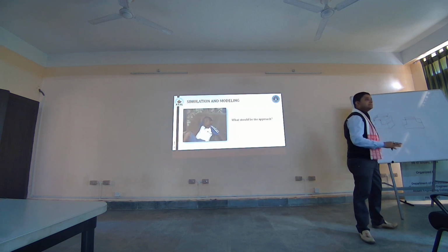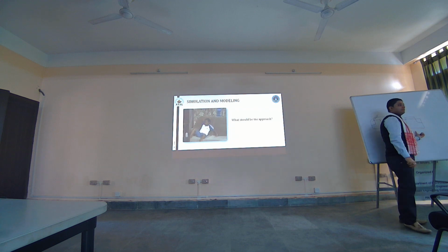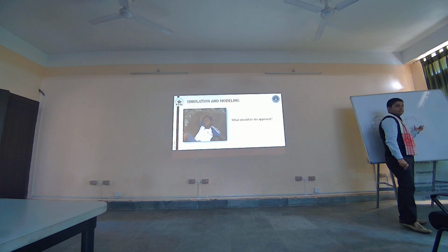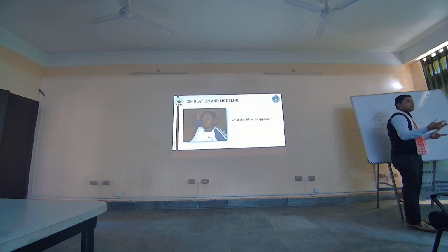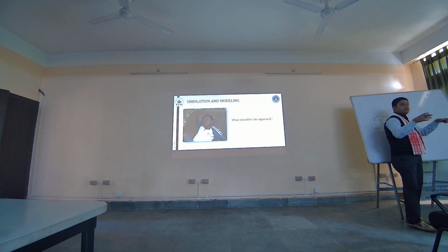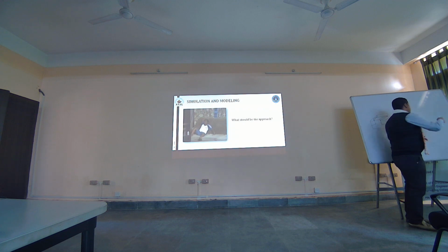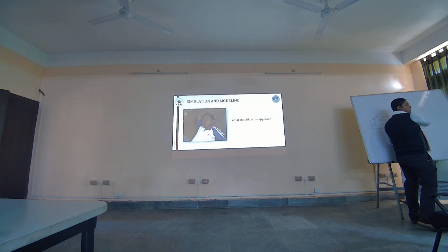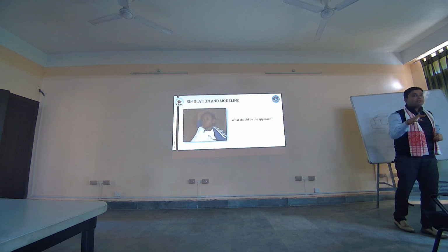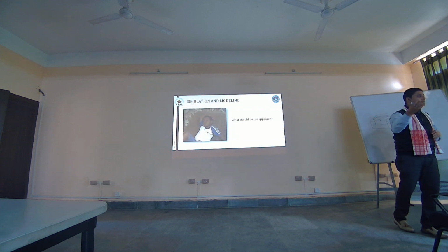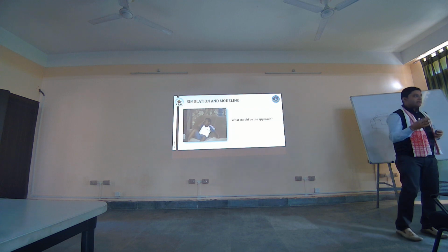Now, the problem with this is that when you are shrinking your device dimensions, short channel effects start to appear in this device, because your gate, which is your third electrode, has lesser control, and your source and drain are overpowering it and have control over the channel. So basically, it is the termination of the electric field which comes from the carriers in the drain over the carriers which were supposed to be controlled by the gate. So now the gate has lesser control over your channel, and you do not want that. That is basically the origin of this short channel effect, the charge sharing.